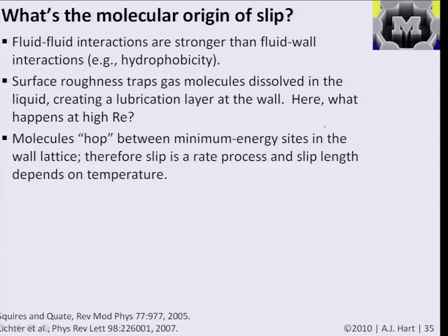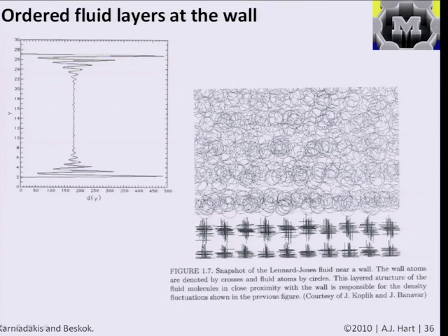And then we can also consider that the actual physical interaction between the fluid and the wall is like a diffusion process, or like hopping of molecules along the surface. And every time the molecule interacts with a certain site on the wall, there's some attraction and interaction, and the fluid above it is kind of pushing it along, and the wall is pulling on the molecule, and the slip length and this behavior can depend on the temperature based on the overall transfer kinetics of the process.